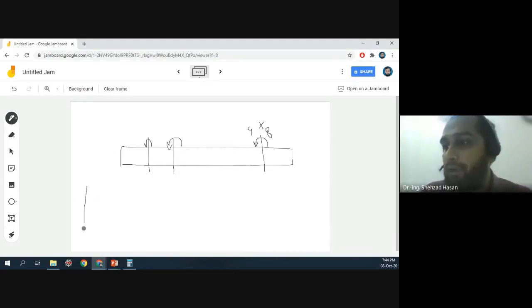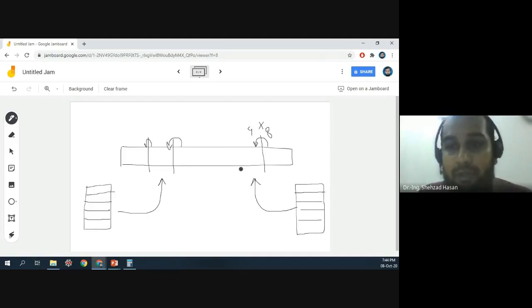So in this way, if I have pixel intensities as a single byte, I can merge them together into a big number and give that as one of its inputs, and another number which I need to add with all of them. For example, if it was 40, I need to create many elements of 40 and give it as the second number. Then this adder is going to work and give me some results. Now, what is that result going to be? This result is going to be the first number added with the first number, the second number added with the second number, and so on.